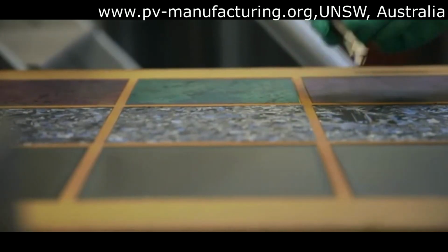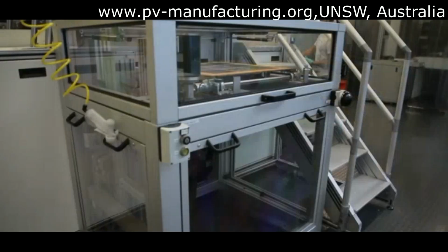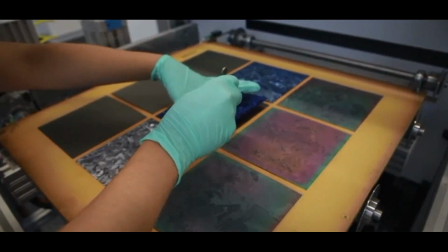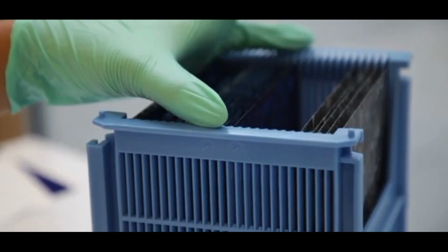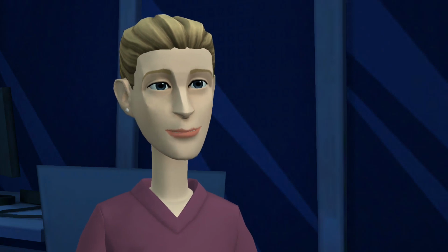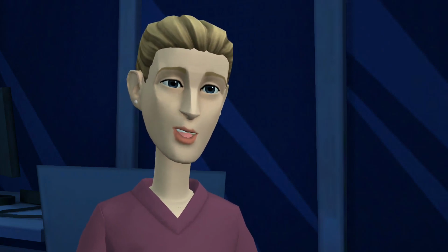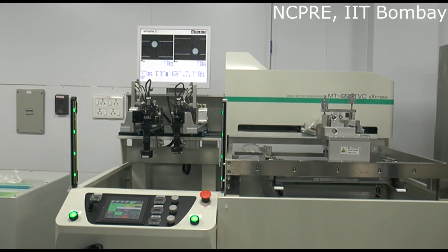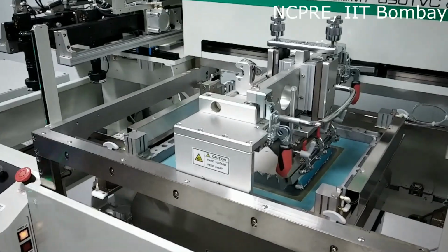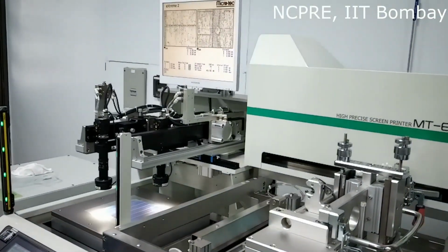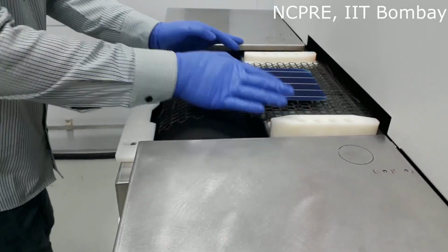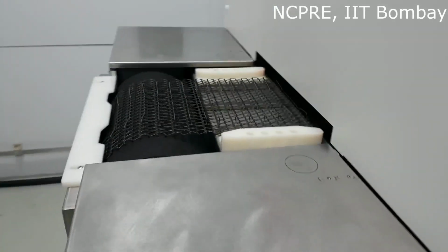In order to further improve light trapping, a silicon nitride layer is deposited on the structure in a vacuum chamber called a plasma enhanced chemical vapor deposition (PECVD) system. Now, the solar cell structure is ready. We just need to make contacts for the external circuit. This is done by a method of screen printing. The wafers are placed on a stage, and then metal pastes are printed through a screen with the pattern of contacts which we design. Finally, the cells are put in a furnace with very high temperature, so that the metal can make good connection with the semiconductor.